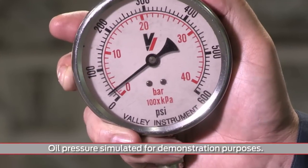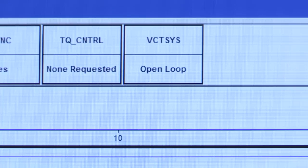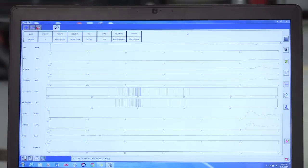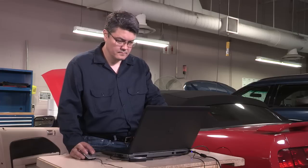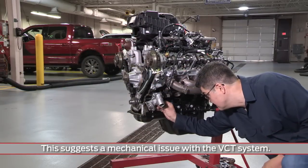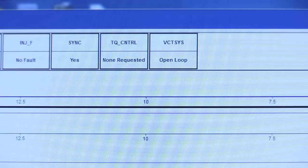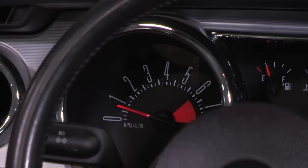Look for a minimum oil pressure of 15 psi at idle. At this point, the VCT should not yet be engaged. If oil pressure is okay and you notice VCT activity while monitoring parameter identification or PIDs at idle, this suggests the concern is not oil pressure related. If oil pressure is okay at idle, drive the vehicle and allow the VCT system to enter closed loop and operate. Then, decelerate the vehicle back to idle.